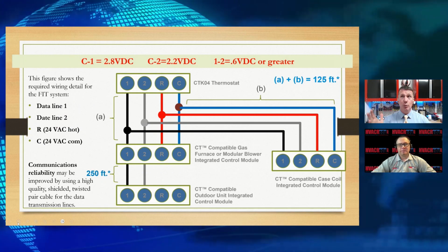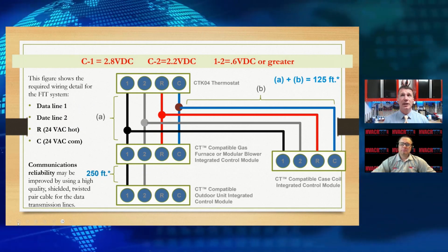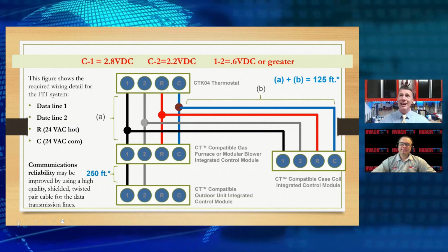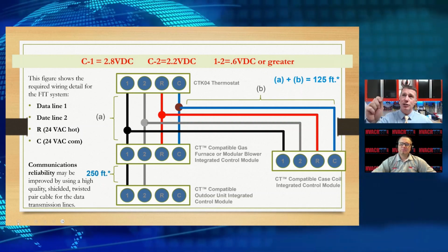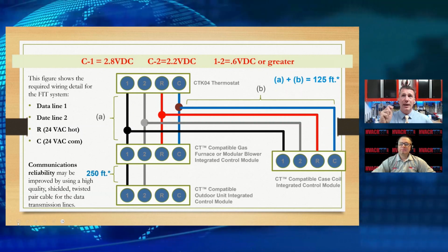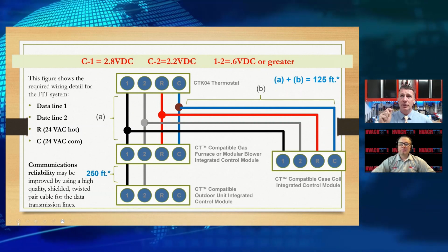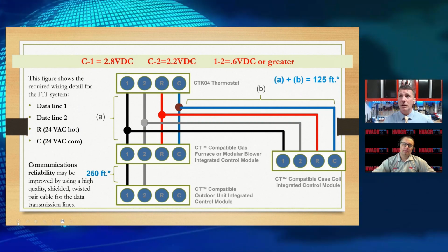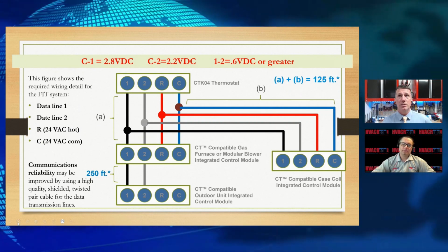So it's super simple to check the bandwidth. If I'm an educator bringing in a new Daikin communicating system and connecting it, I can now show my students how to make sure that my network is good and operating properly. If it's not, this is where you start. You start on the bias voltages.